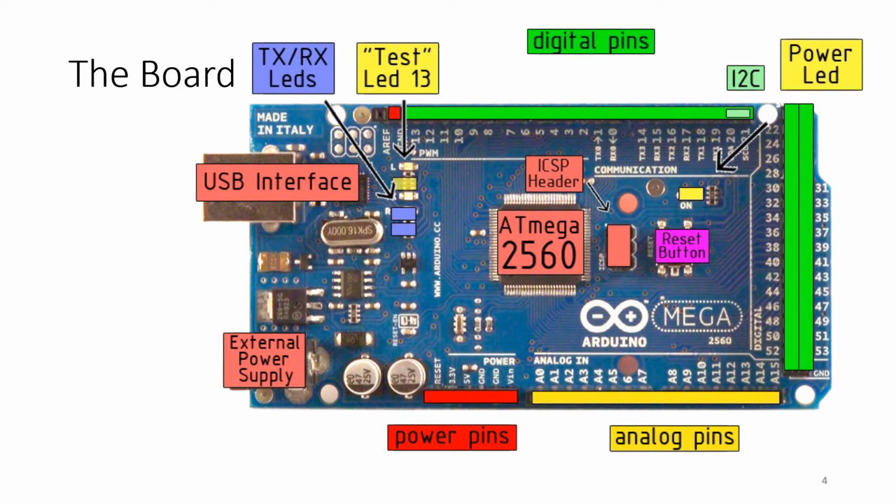The Arduino Mega has several facilities for communication with a computer, another Arduino, or other microcontrollers. The Arduino software includes a serial monitor which allows simple textual data to be sent to and from the board. The RX and TX LEDs on the board will flash when data is being transmitted via the Atmega 8U2 chip and the USB connection to the computer.